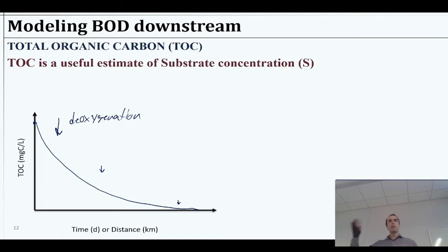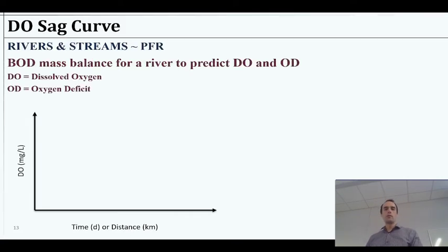When we compare the competing rates, the rate at which deoxygenation is occurring will decrease as the amount of food decreases. Okay, so when we're going to compare this in terms of TOC and dissolved organic matter, then we'll see a graph that does just that in a minute.